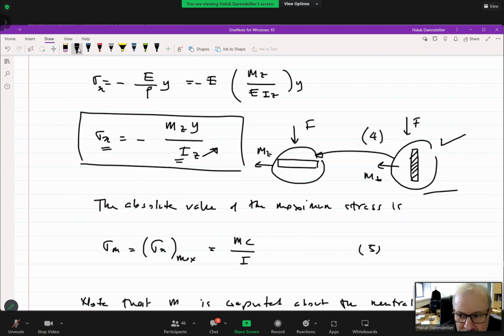That's why such I-beams are used in beams, because we try to remove the material away from the neutral axis. If you do that, for almost the same cost, you have higher moment of inertia. Please keep this in mind. So never use this configuration. You can carry a lower force because you end up with higher stresses, by referring to the equation that we obtained. Okay. Thank you.